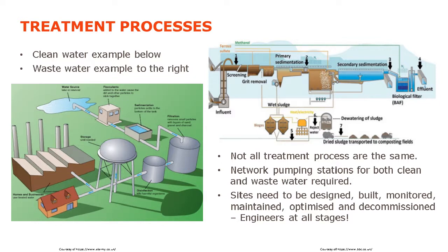As the sludges I mentioned earlier are drawn off the process, the sludges can be used to create energy. So this is a very good energy from waste example, quite raw. The sludges are drawn off, they're heated up, and the gases, methane, are drawn off. The gas could be cleaned up and put straight back into our gas network, powering our homes, powering our industries, powering the site it came from.